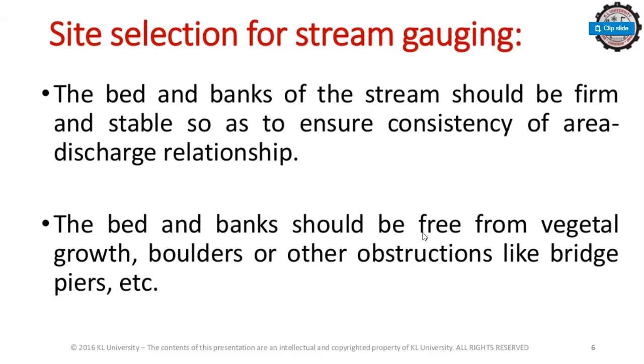After a gauging station has been established and sufficient discharge measurements have been made to determine the stage discharge relation, it becomes necessary to make additional measurements at various stages from time to time to know just how rapidly or how slowly the control is changing. A control should never be assumed permanent until it has been proved so by a number of measurements made after the passage of floods.